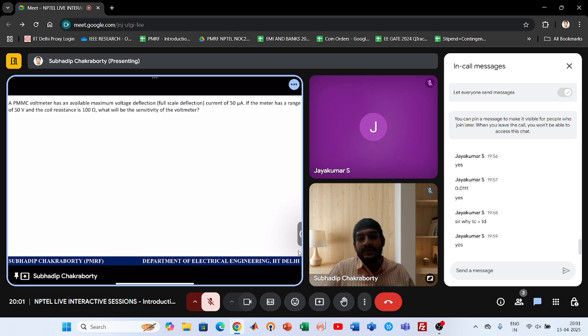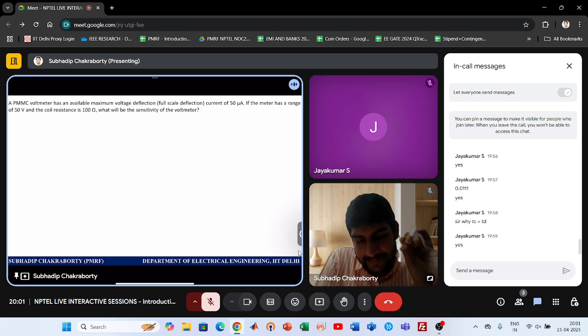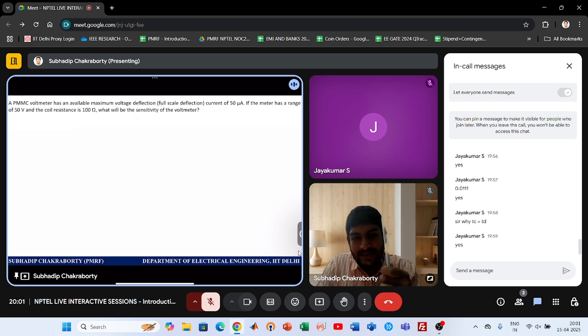So Newton's law. Similarly, the pointer, after getting to that place with damping, if the net force acting on this body is 0, then with damping the velocity, the angular velocity I am telling, will die out. But for it to be stationary at a particular point so that you can see the reading, the deflection torque should be counterbalanced by an opposite torque.